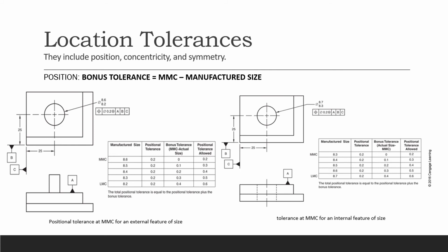I'm going to draw that for you. This is how you calculate, and here is your MMC. MMC minus the manufacturer part is right there. Manufacturer size is right there. That's still pretty good because it's still within the permissible zone. So positional tolerance allowed this much. All you have to do is add this and this, and you're going to get that. Now we have a little more, not as precise as this, so that we can save and earn more money by speeding up the manufacturing processes.